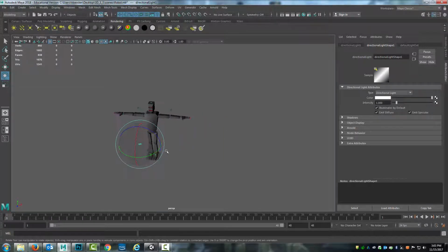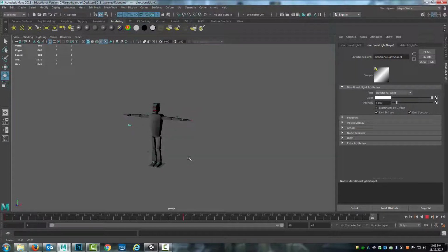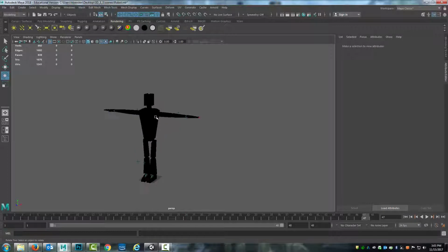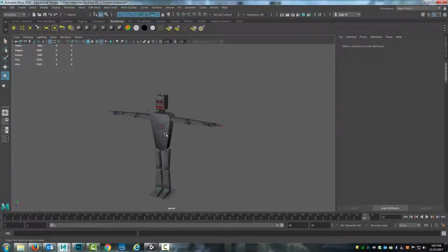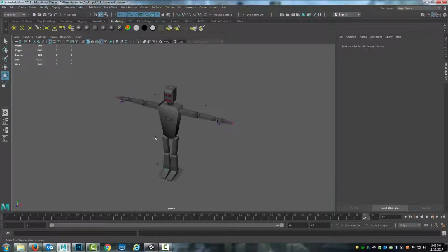But the lights can also be interacted with in pretty significant ways. If I hit the S key here, come to frame 24 and rotate it to there, hit S, now I can animate this light's movement. And so you can see it's moving across the surface. In the same way, I can set up cameras, and I'll hit the 6 key now that there's no light in the scene. I can set up cameras within Maya or within any other rendering engine or game engine to do different functions as well.